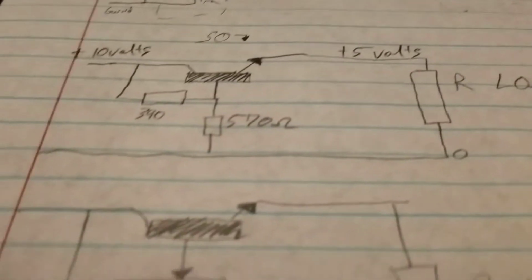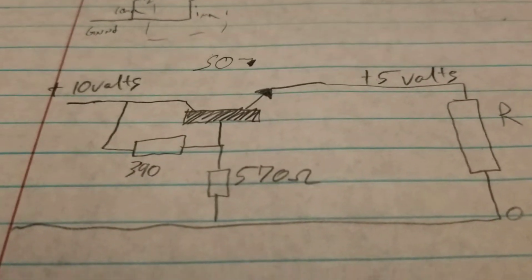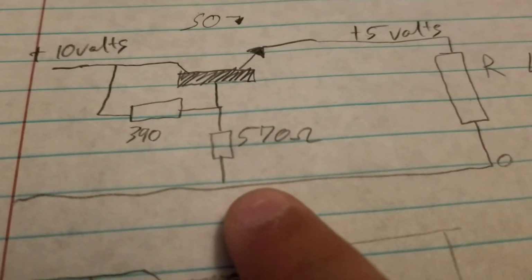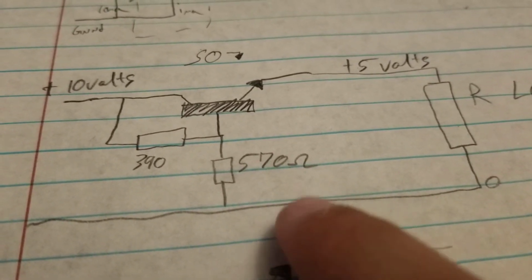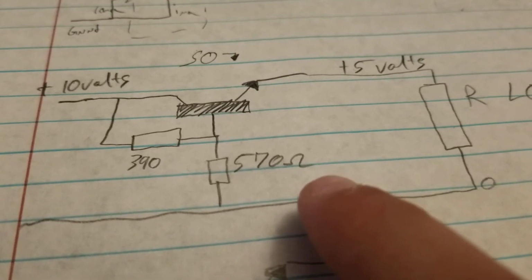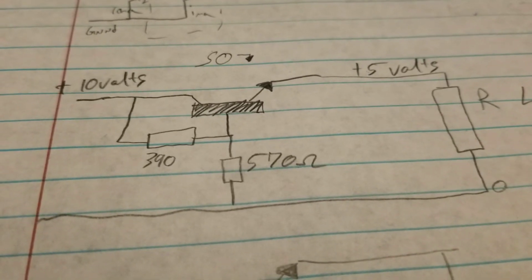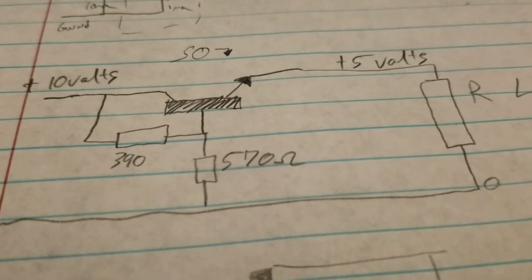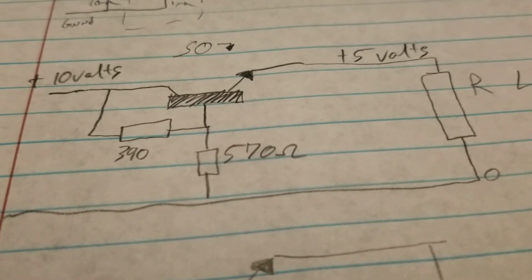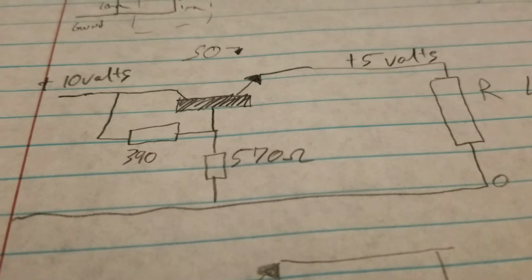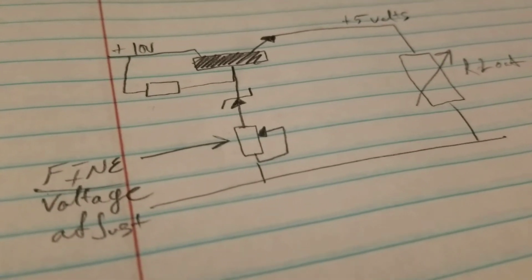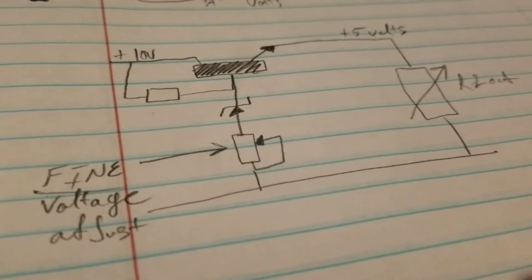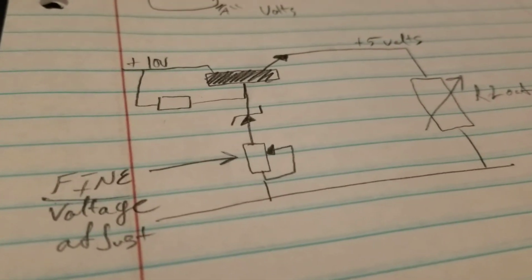If we look over here at this schematic, a lot of these things, like these resistors, if they start heating up due to passing high current, being underrated, or just temperature conditions like out in the field, if it's the dead of winter or the middle of summer, those resistor values, especially the cheap kind, will start drifting in and out of tolerance. With the Zener diode, they don't drift in and out like that too substantially. For practical purposes, if something's strong, a couple of amps, it's probably not worrying about that precise a voltage anyway.